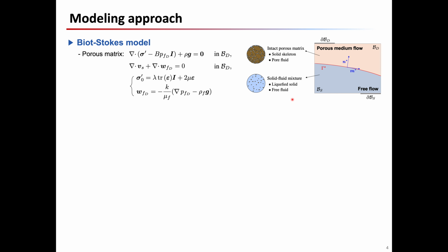The governing equations for the region B_D look like this, which adopts the effective stress principle to capture the hydromechanically coupled behavior, while the porous medium flow is modeled by Darcy's law, where the velocity w_FD and the gradient of pore pressure p_FD have a linear relationship.